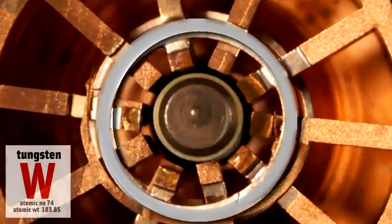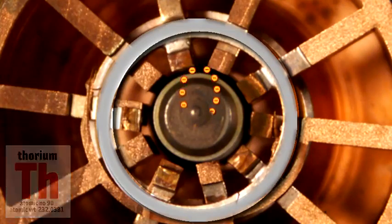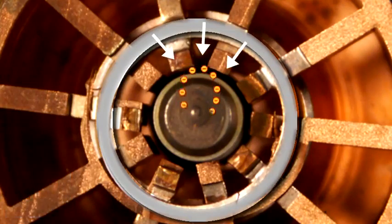The filament is made from tungsten and thorium. Tungsten because it can withstand high temperatures, and thorium because it's a good source of electrons. The magnets bend these electrons so that they swing back toward the center filament. We adjust the magnetic strength so that the now orbiting electrons just brush past the opening of these cavities.